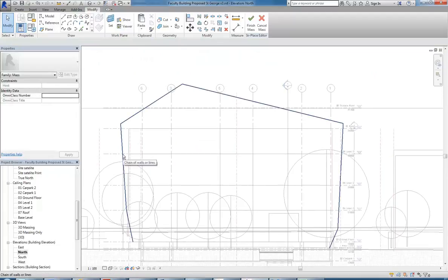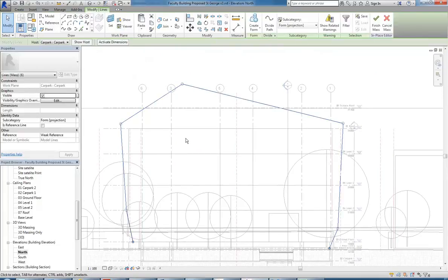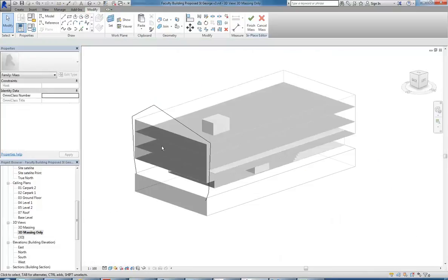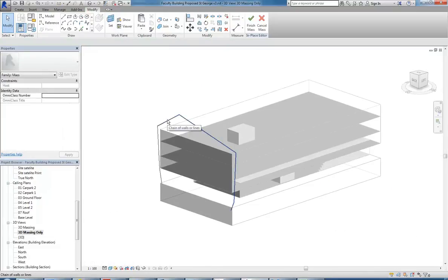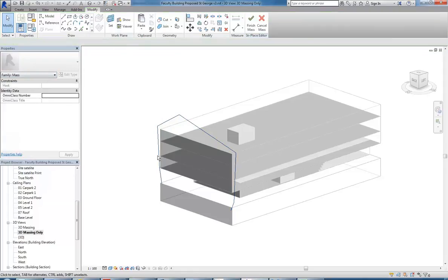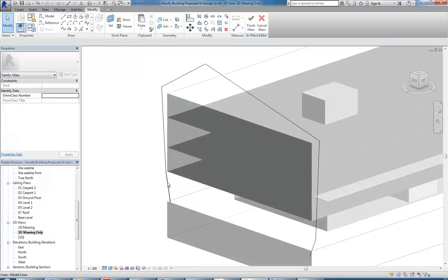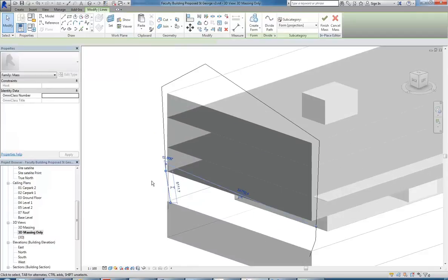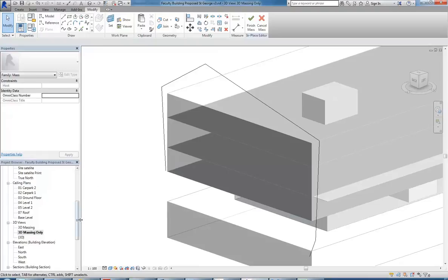So there we go. So you can see there I've got a connected shape on top, but I've got to go now and make sure I get rid of the duplicates. Okay, so an easy way of doing that is just to select the whole thing with a window, hold down Shift, and then see if I can select on top of each of those segments, which should remove the last thing I've drawn. So I should have there 6 selected. 1, 2, 3, 4, 5, 6. Delete, and now, it just didn't do the last one. It's a bit annoying. Okay, so then, that's really frustrating. So I'll go back and draw that again.